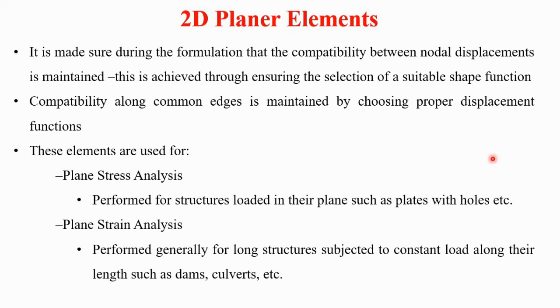These 2D elements are basically used for plane stress analysis and plane strain analysis. Plane stress analysis is performed for structures loaded in their plane, such as plates with holes. When the loading is applied in that plane, the plane stress condition will be there, so in such cases these 2D elements are used.